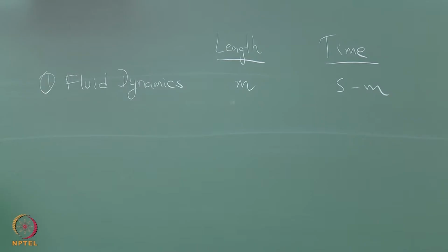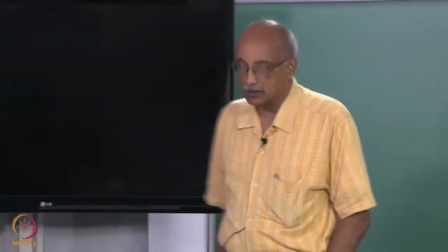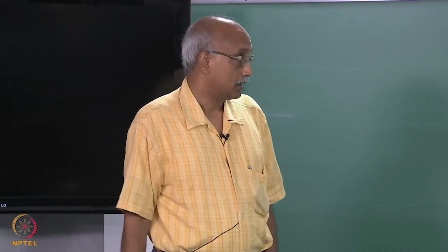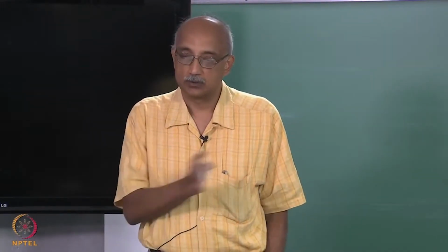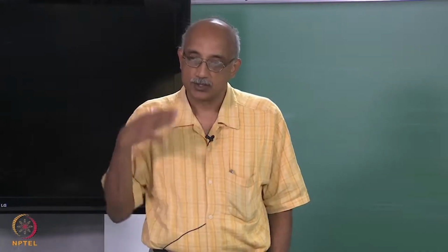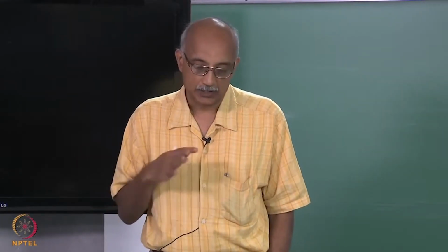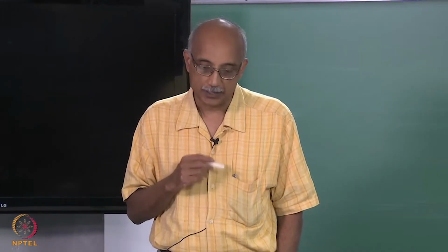It is essentially the time that the carrier gas that is introduced into the CVD reactor has available to traverse the reactor and also establish steady state conditions over the substrate on which the deposition is taking place.